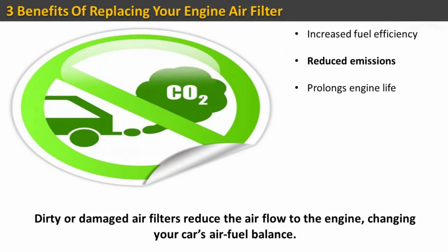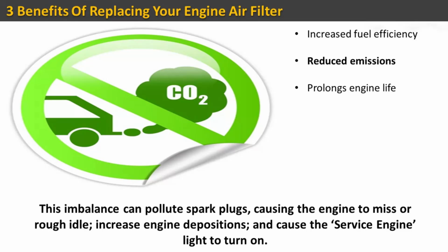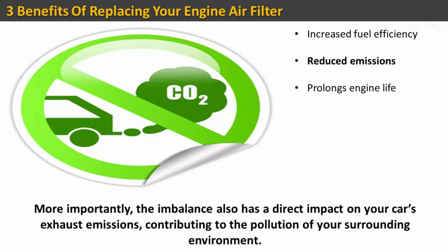Dirty or damaged air filters reduce the airflow to the engine, changing your car's air-fuel balance. This imbalance can pollute spark plugs, causing the engine to miss or rough idle, increase engine deposits, and cause the service engine light to turn on. More importantly, the imbalance also has a direct impact on your car's exhaust emissions, contributing to the pollution of your surrounding environment.